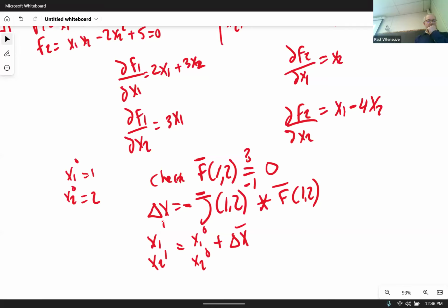Number 5. Why do you always need a slack bus? You need a reference, and you can never know exactly the losses in your system. So that slack bus has to make up the difference for all the line losses. It's going to be able to put whatever P and Q in or out, whatever P and Q is necessary to make sure all the system line losses are accounted for.